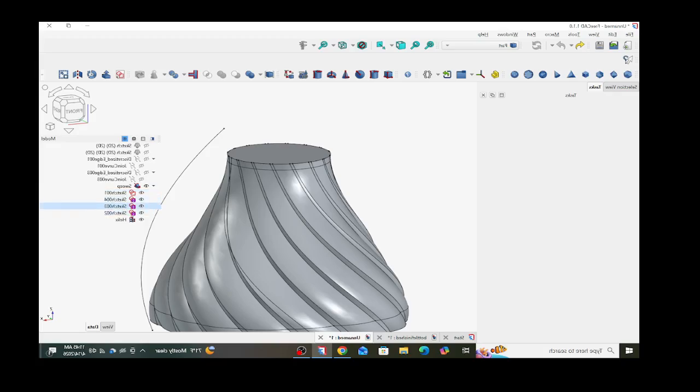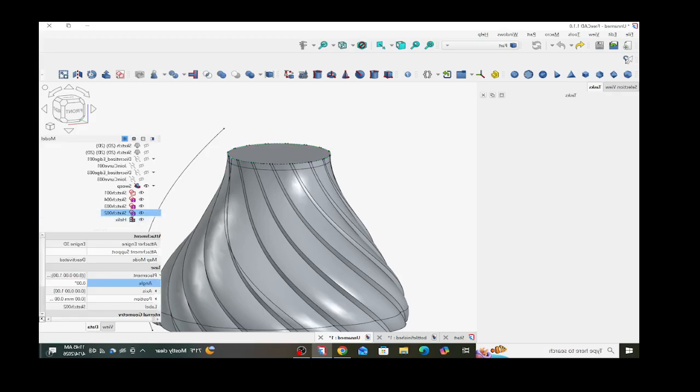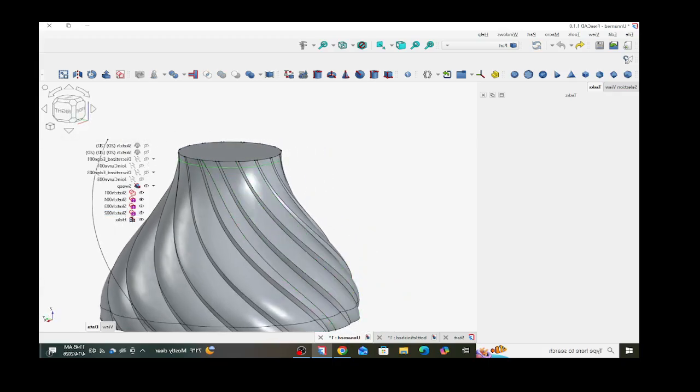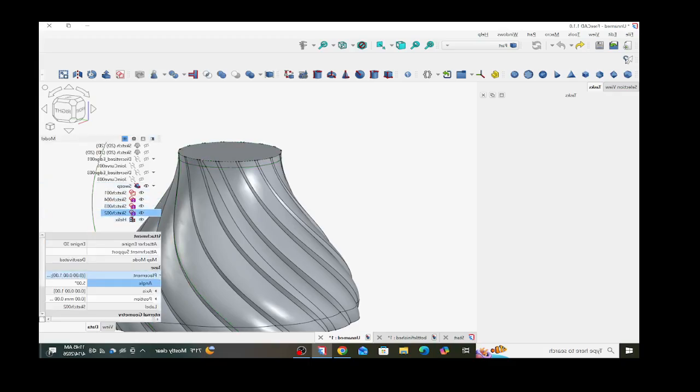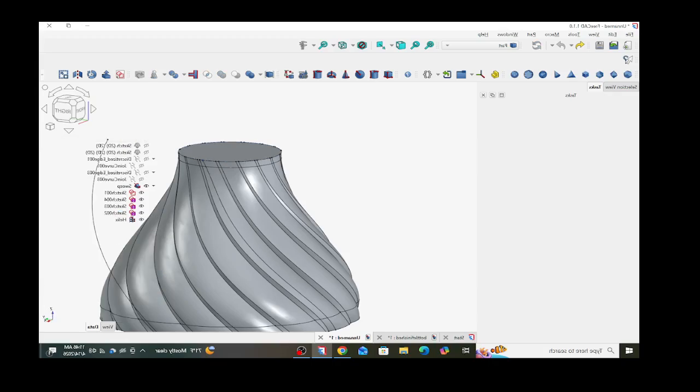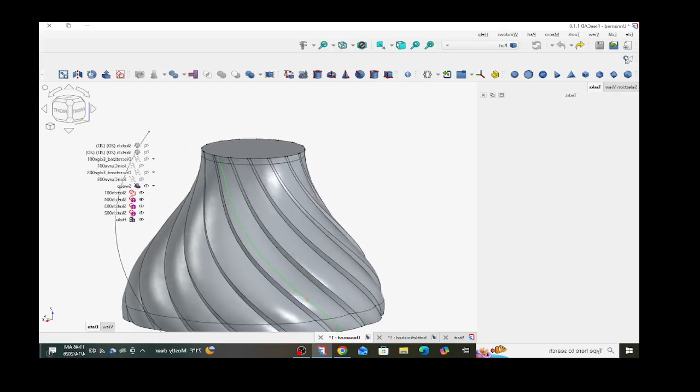Our top sketch, which is sketch 002, we're going to rotate it about 5 degrees. And that's to create tangency with this line. It's actually too much. I think about 4 degrees is what we want. That's to create this seam line smoothness.